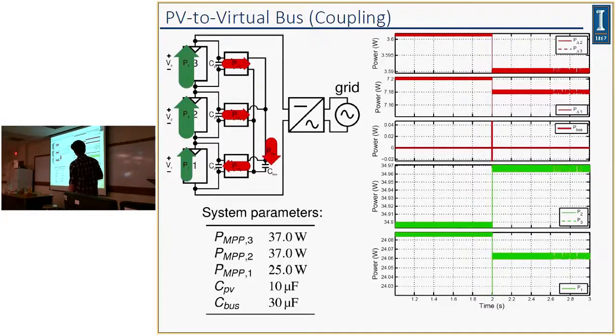And as a result, that changes the state of those two converters in addition to the state of that corresponding panel. But for a brief moment of time, the bus capacitance is sourcing or sinking that amount of power. And that's just because these converters are inductive by nature. And if you think about it, for those of you taking 598, whenever you have a load step for a power converter, the capacitor sources that load for a brief amount of time, right?